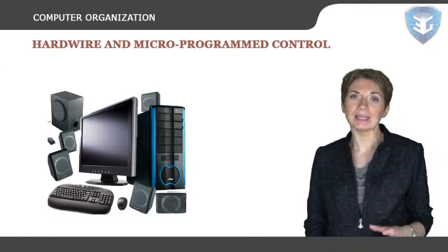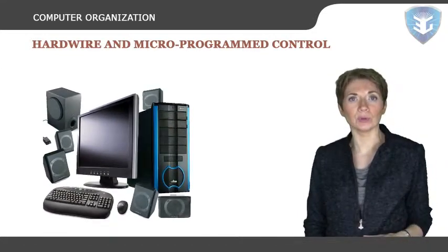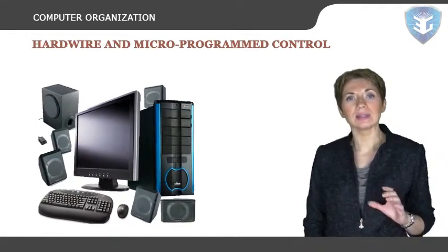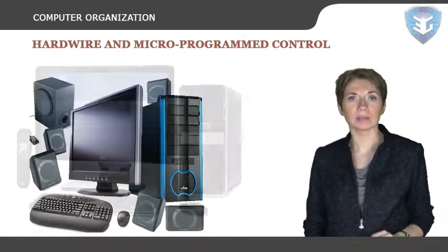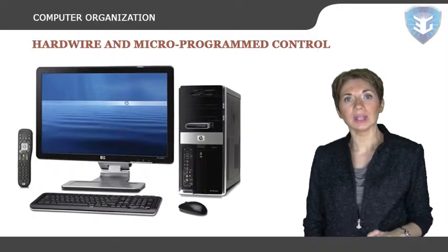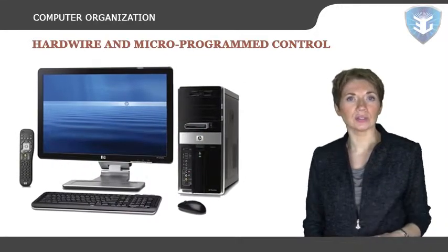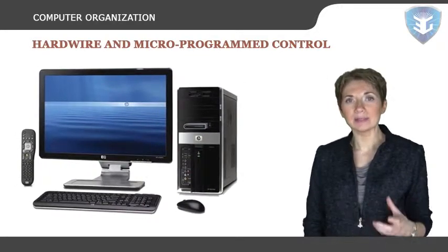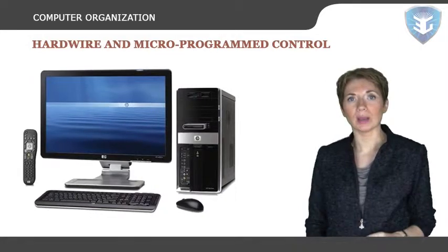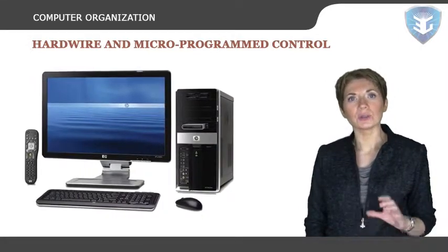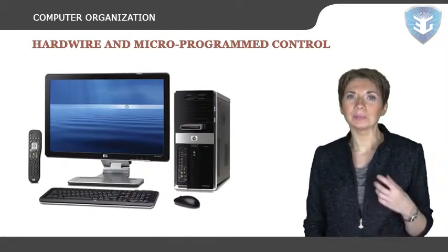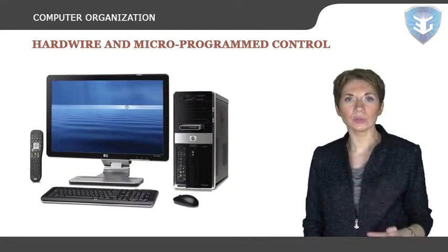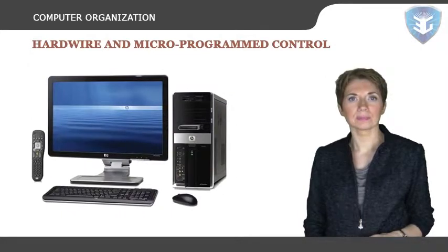In fact, taking the basic computer as an example, one notices that its 4-bit opcode permits up to 16 instructions. Therefore, one could add 7 more instructions to the instruction set by simply expanding its microprogram. To do this with the hardwired version of the computer would require a complete redesign of the controller circuit hardware.